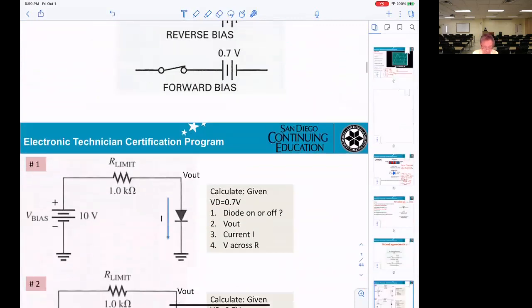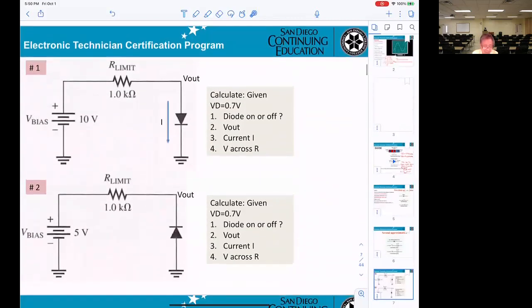And when you're working with the diode, remember, when you say the diode is on, you cannot see any diode anymore. In this one, I know the diode will be on. So when it is on, you must substitute the diode by a battery, plus, minus 0.7 volt.